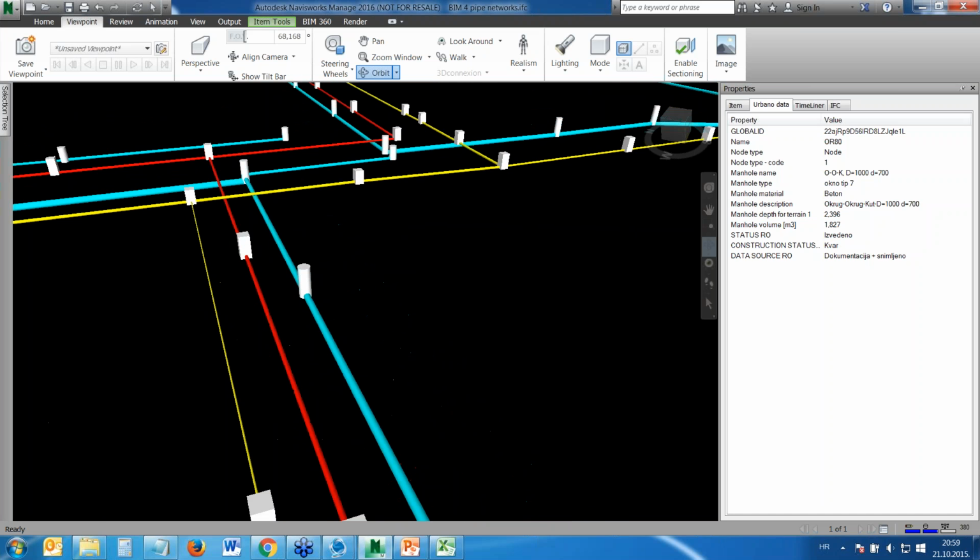Of course, as I showed you, you can do it in Urbano as well, because you can make this 3D pipe style. But with this IFC export, you can send it to Navisworks or to other software even. You can send it to people outside of your company without sending them the DWG file. So they cannot change your design, but they can really look into it.